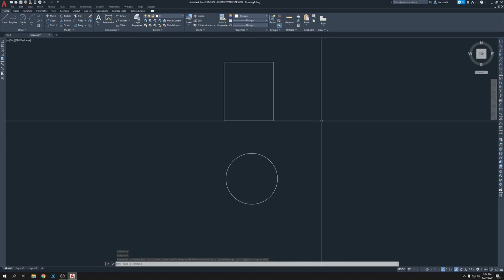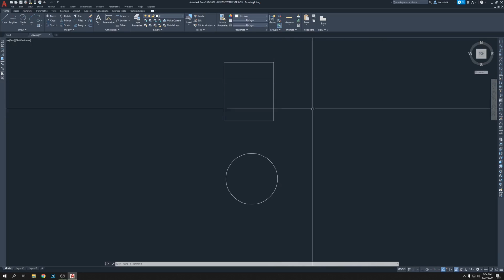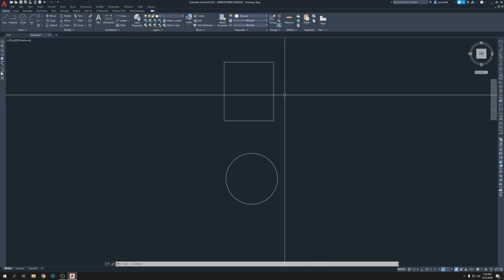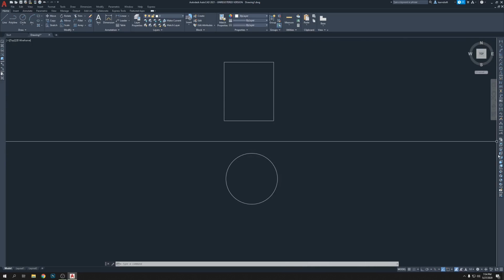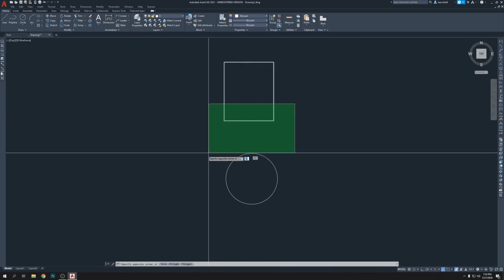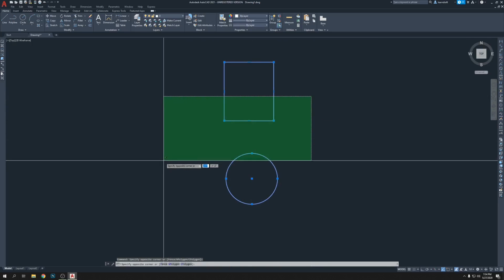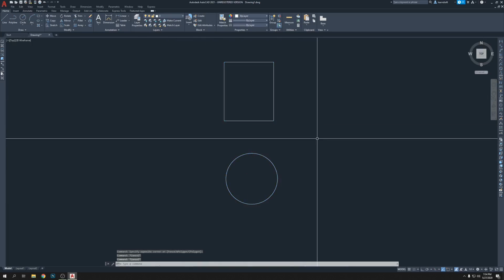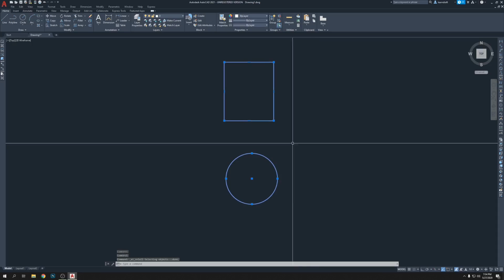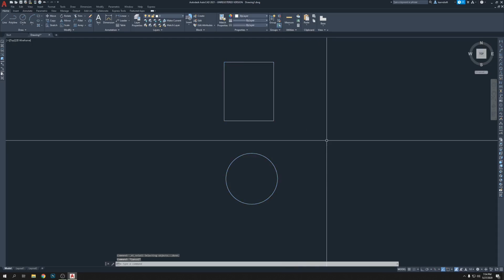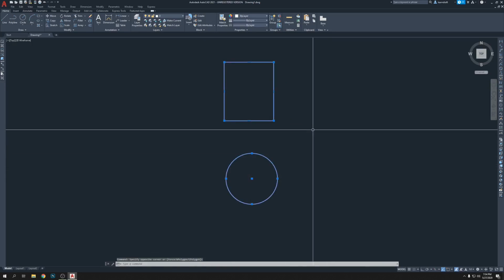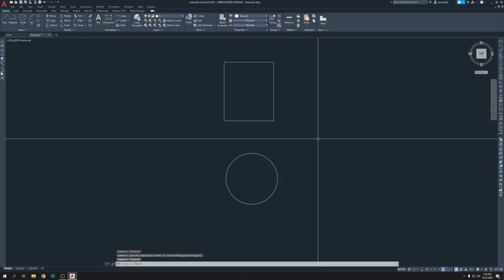This is how you need to deal with it in the future. When you need to go to a different view to see something from the side, from the front, from the back, these are the tools you need, and you know how to bring them up. So I'm going to select these two like this, or Control A. For now I can press Control A and delete. If you don't want to delete, just press Escape, the ESC button on the keyboard's top left corner. Select, escape, select and deselect.